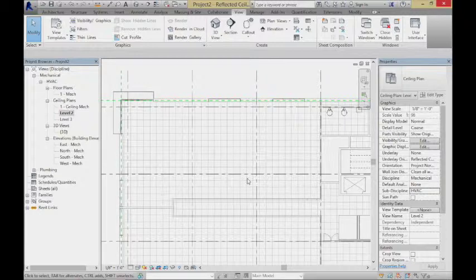So, let us say the way the space is divided, kind of this half of the floor and that half of the floor is separate. There's a hallway in here. Let me guesstimate that, maybe on this side we needed about 3,500 cubic feet per minute. I'm just trying to remember. We can do the calculation, but I'm guessing it's around 3,000 or 3,500. Okay, same thing over here. So if I'm going to use terminals that are rated at 500 cubic feet a minute, you can sort of see what the rating is. That would require 7 of them. Okay, 7 returns and 7 supplies. But let's go ahead and figure it out.